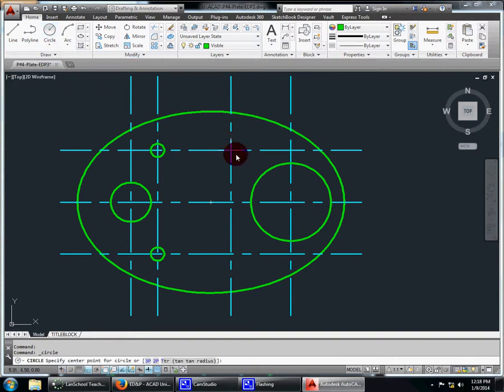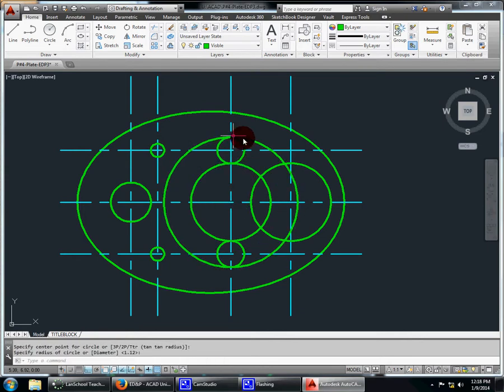So I know I have 2 circles with a radius of 0.38 here. Enter key again, intersection with my mouse, enter key again, there's the perfect size. Next I know I'm going to have a circle going here, and a circle going here. It's going around. So circle again, intersection to intersection, enter, intersection to outside intersection. Great. And I also need to add in the center one.